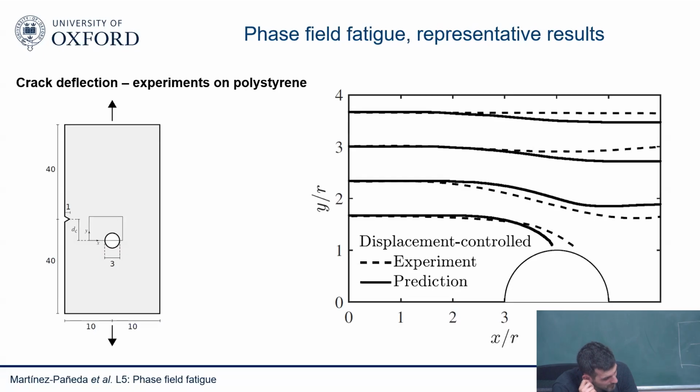I think if the holes are sufficiently close, it will see one of them. But it's true that the stress state will be such that in theory it should go straight. Any minimal disruptions, some sort of microstructural phenomena, could matter. You could try randomizing the material properties a little bit in the simulation, and see how much you need to randomize them for the crack to go to a hole versus going straight. If you run the homogeneous simulation, you should see the crack going straight. I have not run the simulation yet. I'll do that. Yes, it will be interesting.